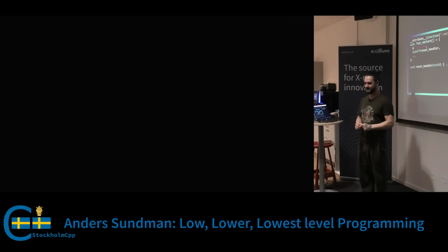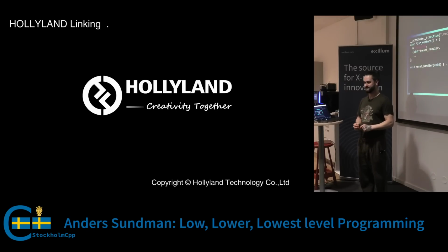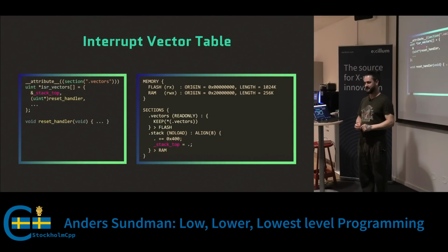Imagine you would like a segfault if you try to write to a null pointer. No, there are no segfaults if you don't have a memory protection unit, which is the thing that segfaults you. This CPU comes, I think, both with and without. I don't know which one this Arduino has, but if you have writable Flash without the memory protection unit, then that's bad.